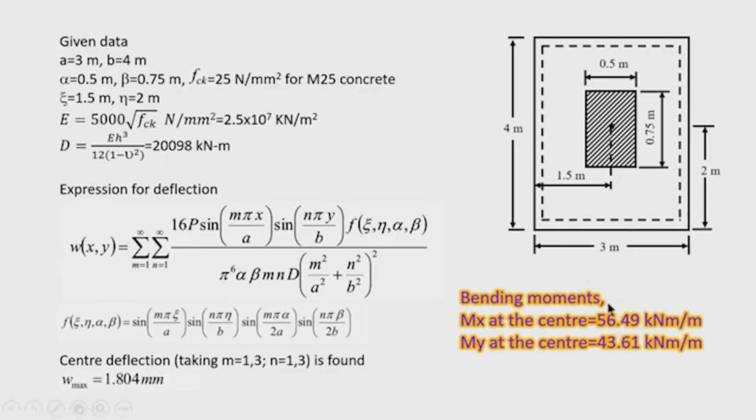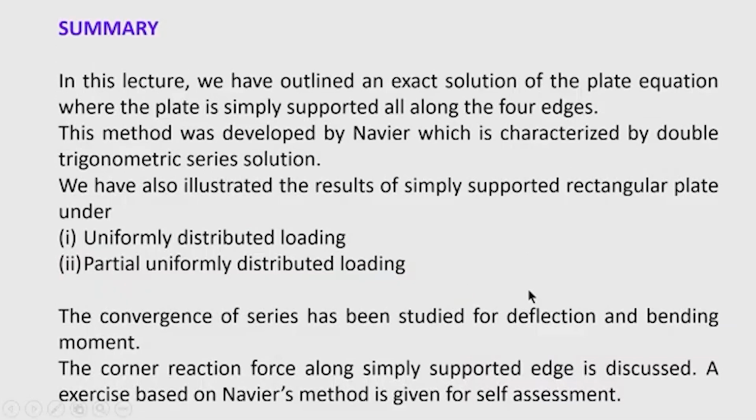Okay. So, let us summarize what we have done in today's class. In today's lecture, we have outlined an exact solution of the plate equation, where the plate is simply supported all along the 4 edges. So, actually Navier's method is an exact solution, and it is a very well known analytical method used everywhere.